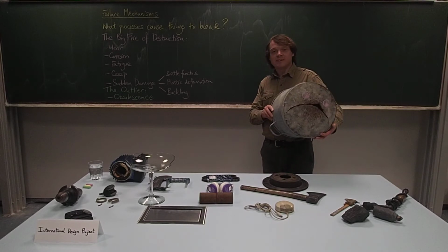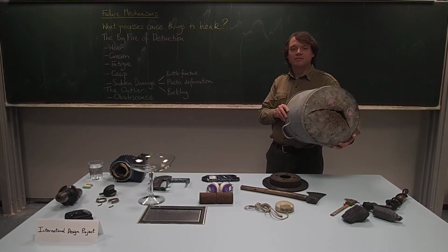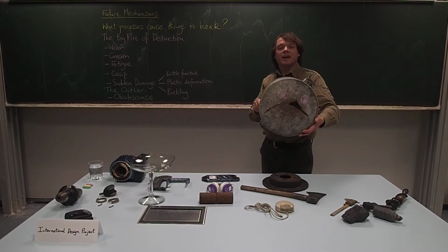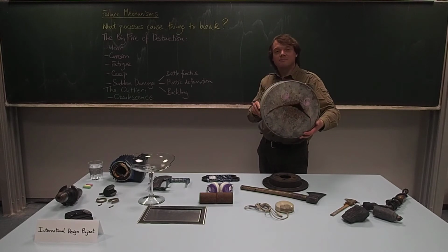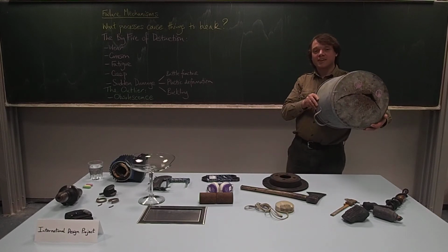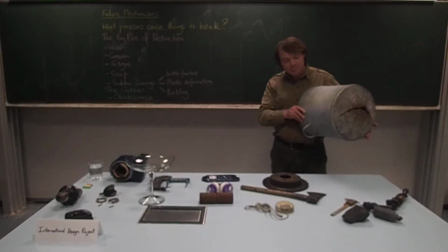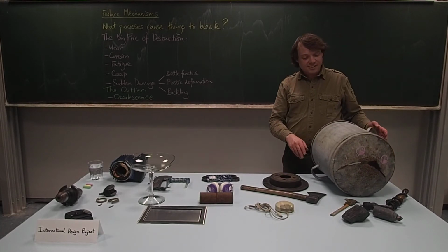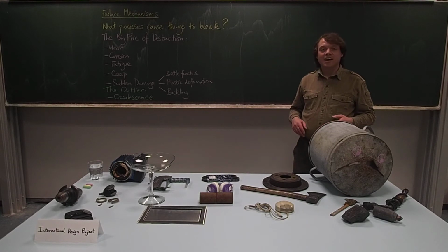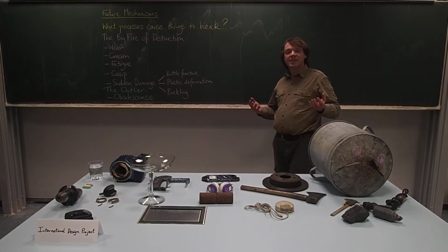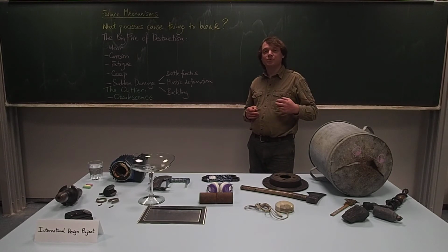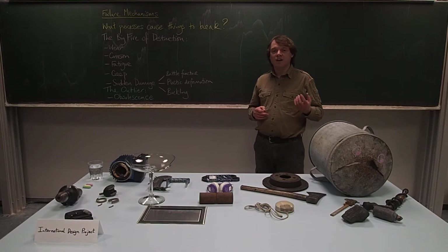Probably then it's been loaded by putting stones or wood or something in it, and eventually it's split open. And you can see here, it's because the bottom's got so thin, it then hasn't been able to support the load, and it's left the bucket looking very sad. Some people might ask why this has happened, when you can see that the sides of the bin here are still galvanized, so they're still covered with zinc, and the zinc is more reactive than the iron, so it ought to corrode in preference to the iron and protect the iron.